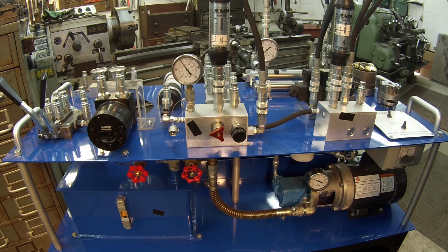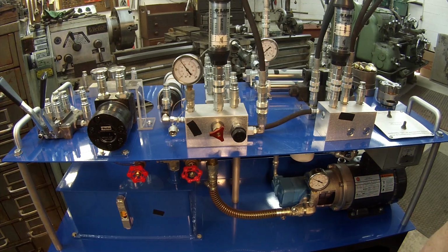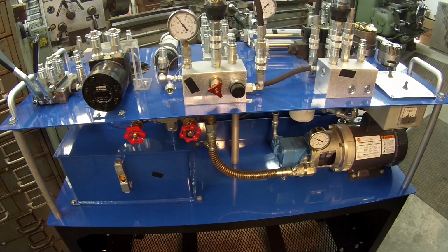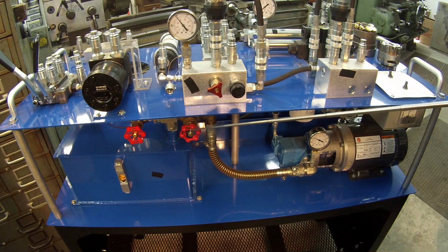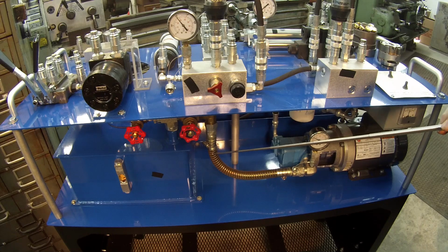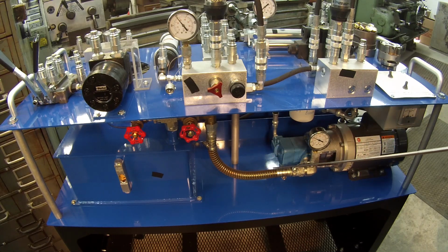You want to do that? Adam's going to demonstrate that. What he's going to do first of all is start shutting this valve off a little at a time. And what you're going to see is little vapor cavities start forming in this hose right here. And what I'm doing is starving the fluid into this pump, and the oil actually starts boiling. That's those little vapor cavities you're going to see right here.